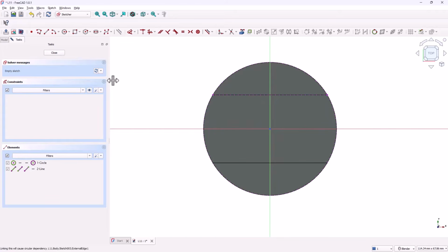Grab the Polyline tool. Begin by drawing a horizontal line that starts from outside of the circular edge and ends on the circle edge. As you draw, a small red hyphen will appear, confirming it's horizontal, and a dot on the arc will show when it intersects the circle. Without exiting the Polyline tool, press the M key repeatedly to toggle drawing modes until you see a tangent arc preview. Drag the arc to the opposite side, ending it at the far point of the reference line,